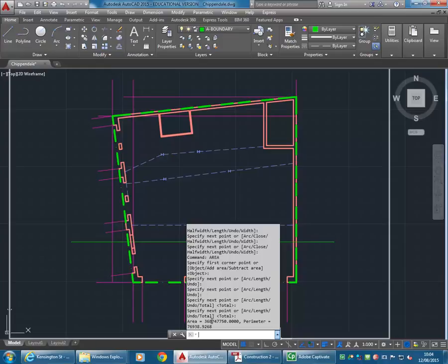So when you get a number like this, just move the decimal place across 6 places. So 1, 2, 3, 4, 5, 6, and that gives us the number. And you should always, just in the back of your mind, think what sensible sizes would be. And if you end up with a figure like 3,000 square metres or 30 square metres for a site like this, then alarm bells should be ringing, and you know you're a bit out.